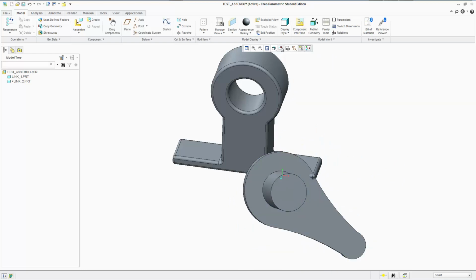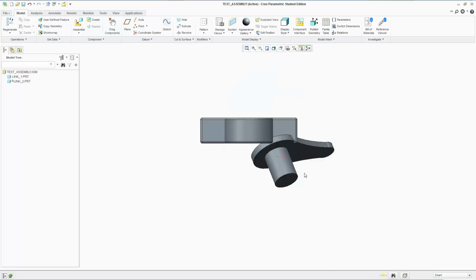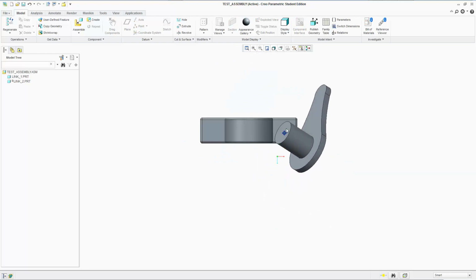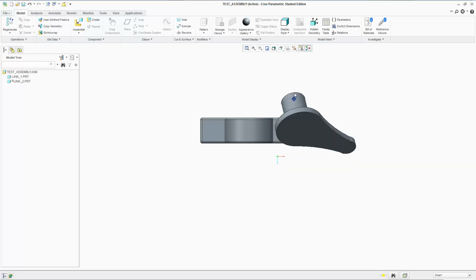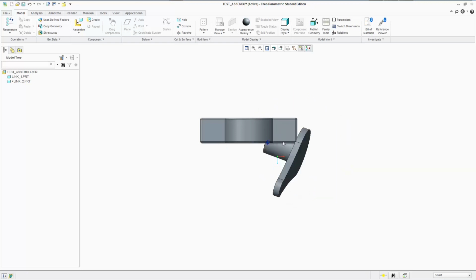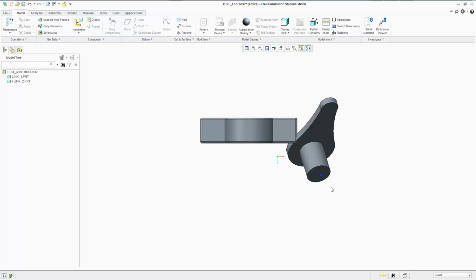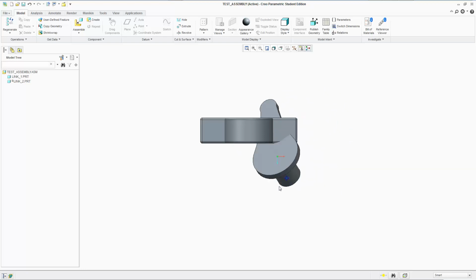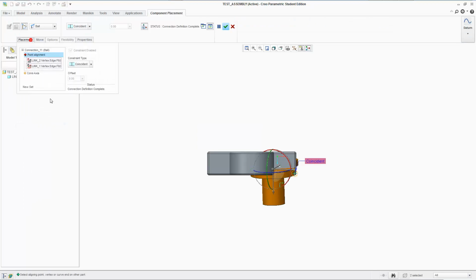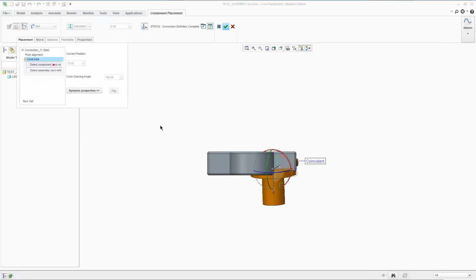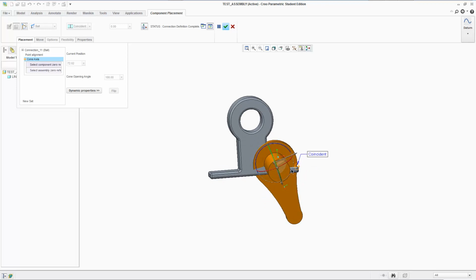So to properly explain the difference that it's gonna make once I go further, watch this. If I go up, forward and backwards, it's allowed to rotate. When I go sideways, it's allowed to rotate. When I go diagonally, so I can go in any direction right now, and it's gonna allow me to rotate. But then there's something called a cone of axes, and with this I can limit this. So for this, it's asking me for a zero reference, zero motion axis for the part.